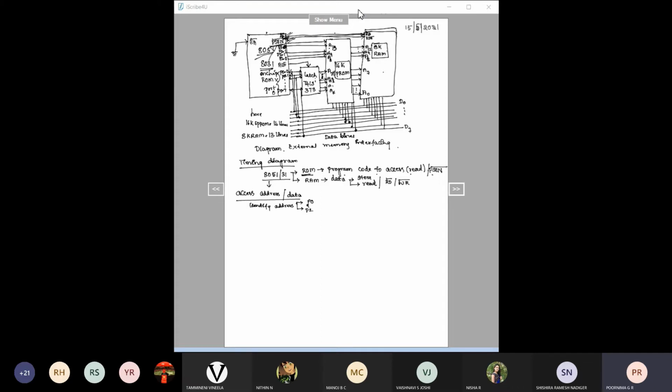Depending on what is the capacity, the number of port lines will vary. So whenever this port 0 it is using, it is a multiplexed bus. It has to distinguish whether it is address or data. So whenever the 8051 has to address, it makes use of ALE. And port 2 directly need not be demultiplexed. It will be address only until PSEN bar becomes 0. This you have to remember carefully, and through the diagrams you have to understand how this will work.